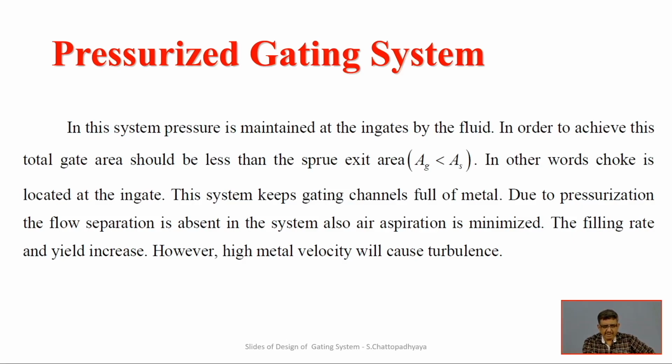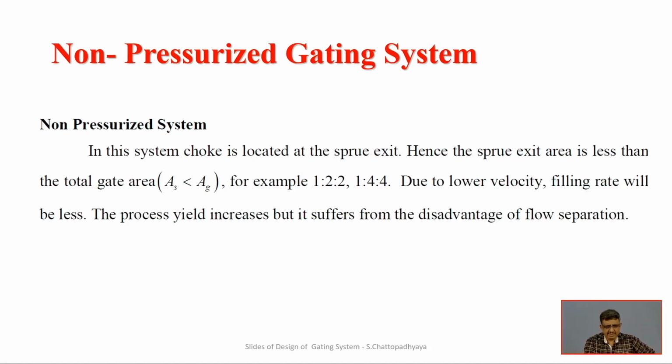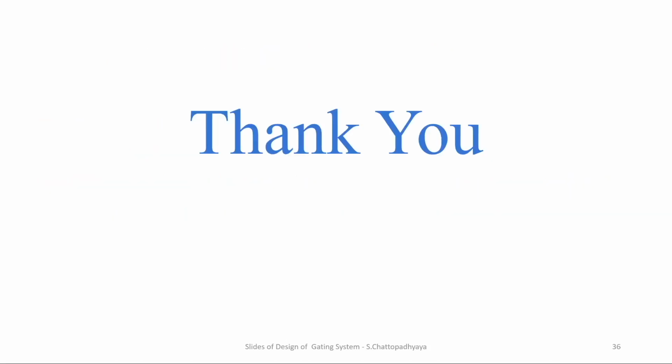Choke is another part in some of the castings, but here with the pressurized one, one can find that no intricate part of the mold is starved of molten metal. I am not going into those details. Non-pressurized or gravity fed gating systems are another type, and the choke and other things have their relationship associated with that. There is no point in going into the detailed parts of choking strategies, choking happening, and strategies to prevent that in a short introductory video.